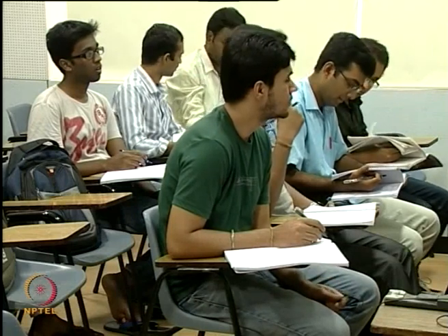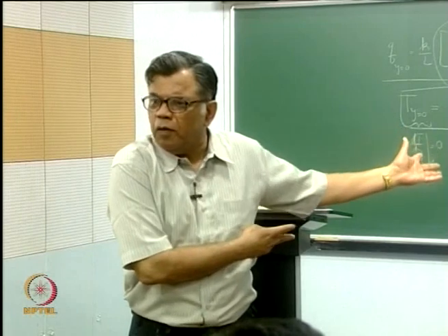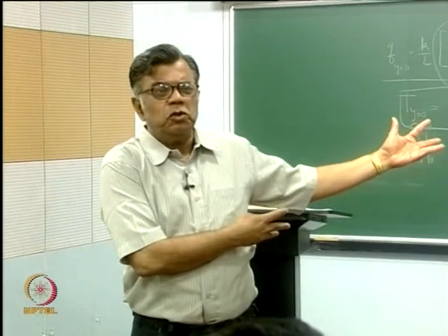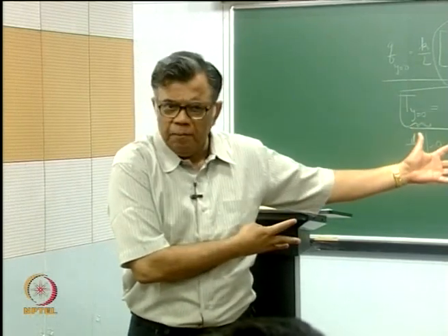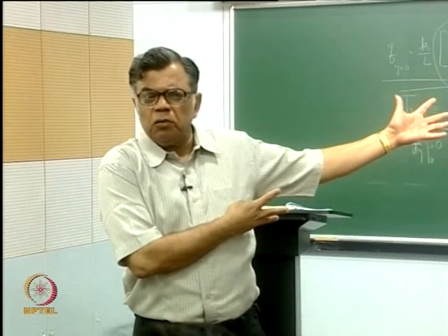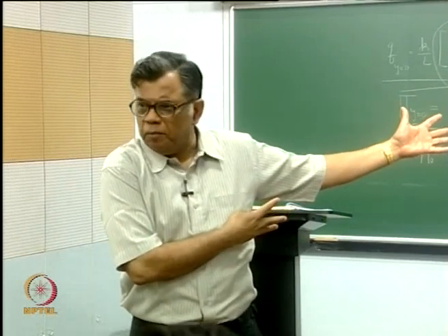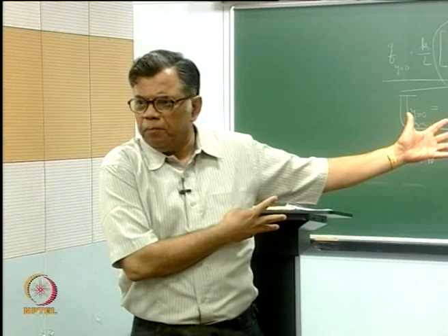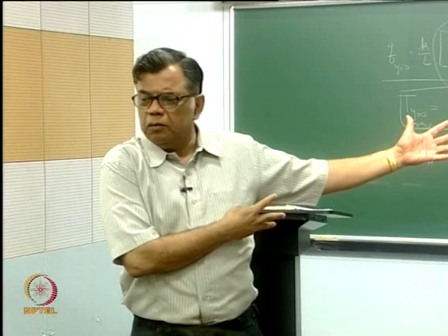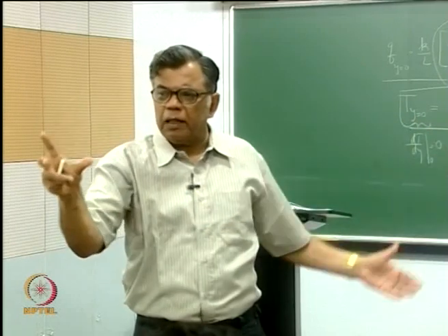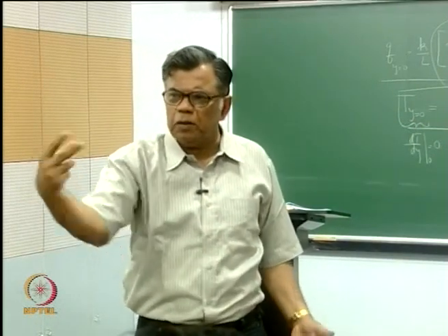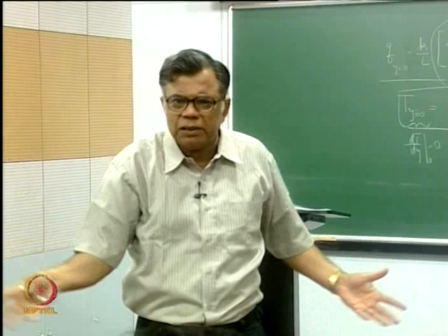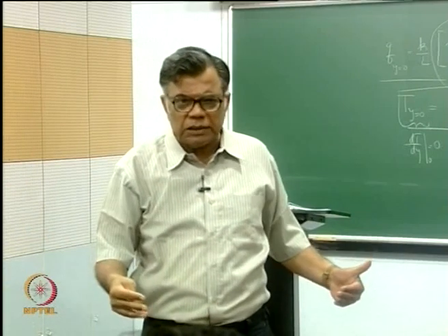Now, I am giving the recovery factor in a simple Couette flow, which you have solved by hand. The complete set of Navier-Stokes equations is not a boundary layer flow, it is a parallel flow. You took the governing energy equation, including a term which you didn't know what it was, but du by dy whole squared did not cancel out. So, you took that into consideration.